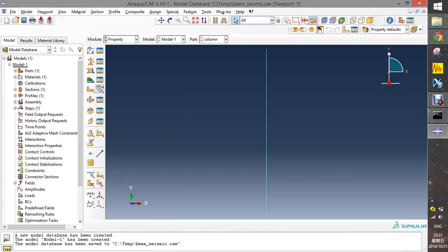And then we need to assign the beam orientation, because we have just assigned the beam depth and beam width to be 0.5, 0.5. But in most cases, the beam depth and the beam width are different. Suppose I have a 0.3 meter width and 0.6 meter beam depth.